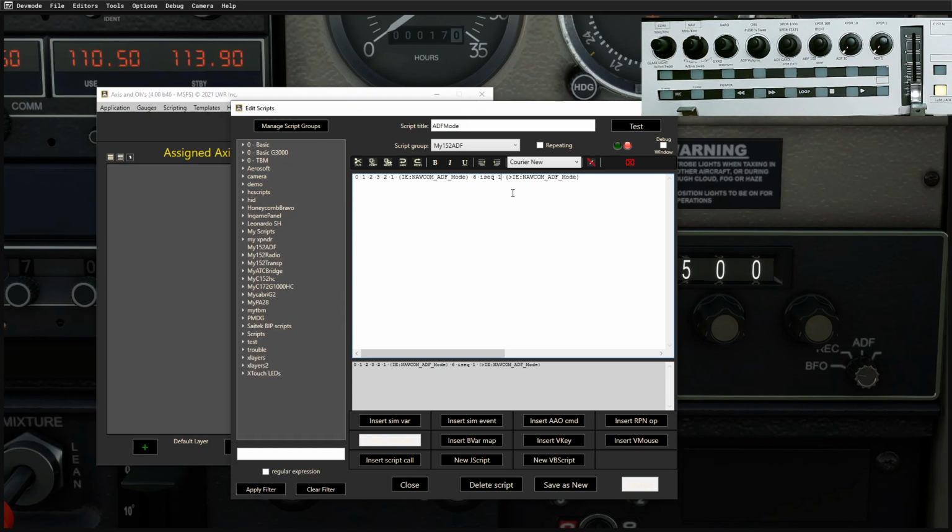Now I don't want it to write a 1 in. What I want it to do is to run along here, find a match, pick up the next one in the sequence and write it back into the variable, which is what this is about. But unfortunately what would happen is if it was in mode 2, it would get to here and it will put mode 3 in. It would never get to here. As soon as it found that, it would be satisfied.